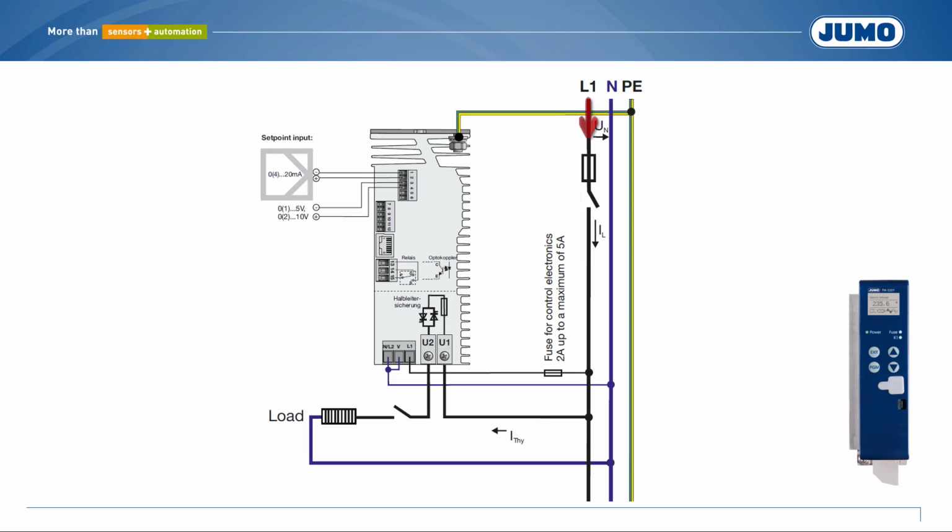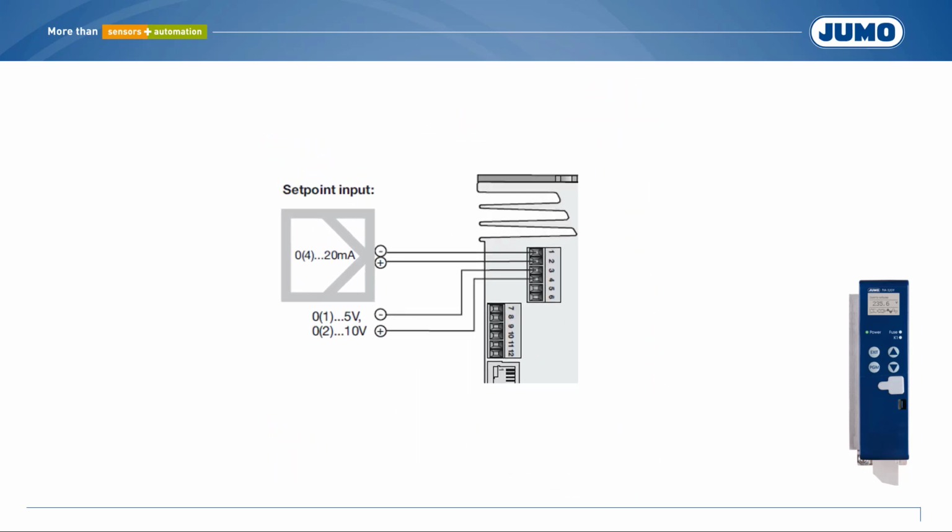The controller is operated via a fuse for line protection. The supply voltage is applied via a microfuse to supply the control electronics. The supply voltage is also connected to the heating element via the thyristors. The additional switch may become necessary when using an interface such as Modbus, Profibus or Profinet. It enables voltage disconnection of the heating element while the interface remains active. The power is requested via a 4 to 20 mA signal.